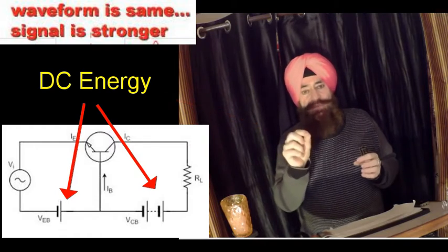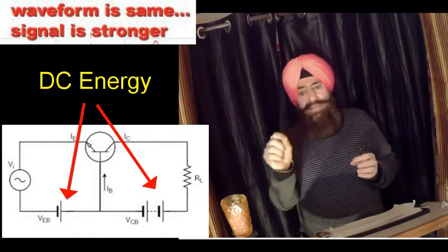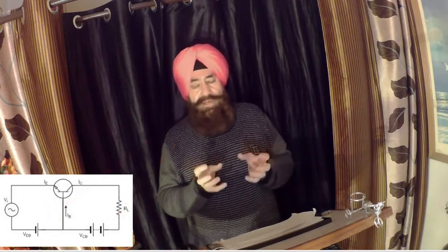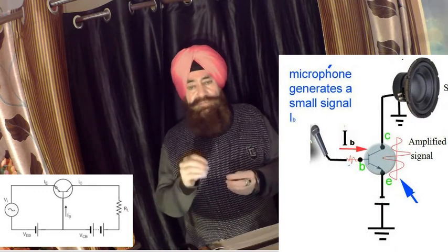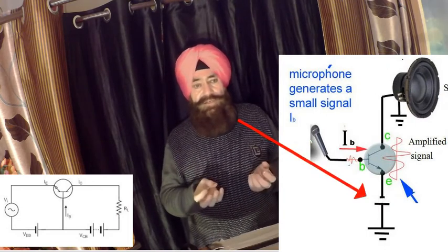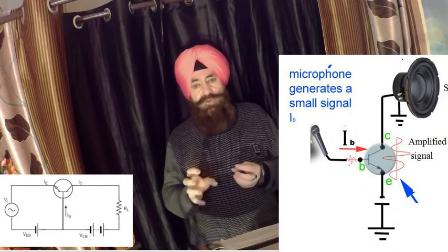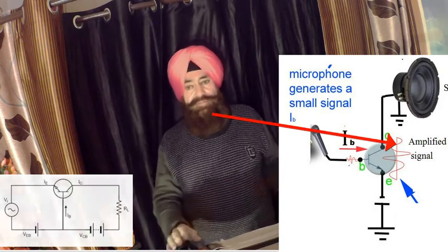DC supplies mean DC biasing at the emitter, at the base and at the collector. The transistor needs some DC voltages at the base, at the emitter and at the collector. You can say the transistor needs the DC biasing for operation and then it works for the AC signals. The analysis or design of an electronic amplifier therefore has two components, the DC portion and the AC portion.